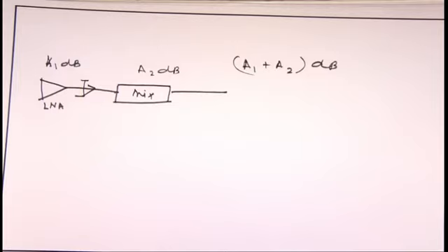So, always remember, when you design an LNA, please also consider a mixer. Why? The first one is the impedance matching problem. Second problem, LNA output will give you a 2.4 gigahertz, okay, or 5.6 gigahertz, and you do not know about the pin package or the PCB trace, all those impedance matching parasitics, you will be in trouble.